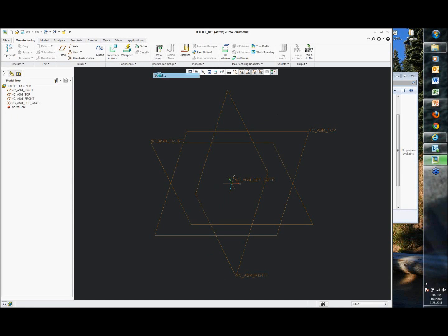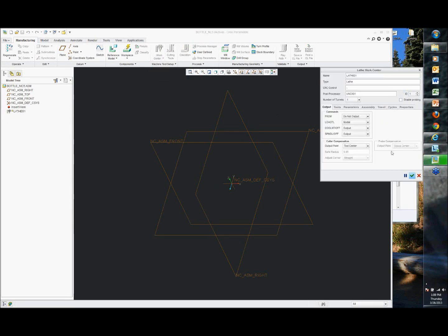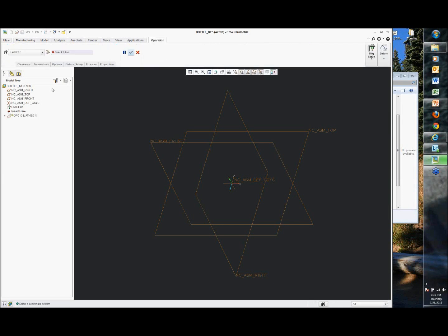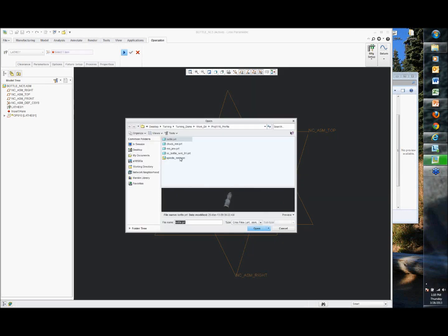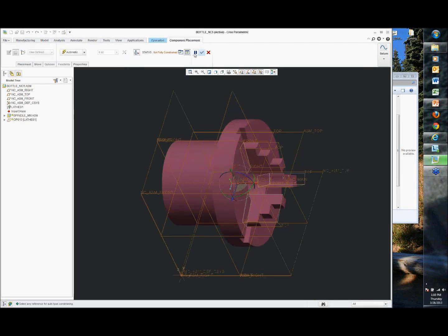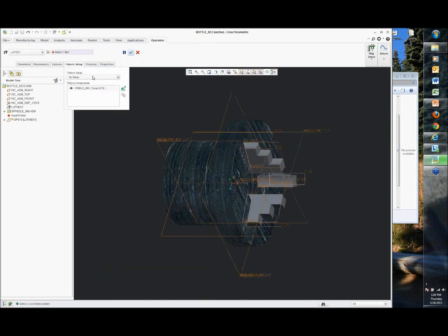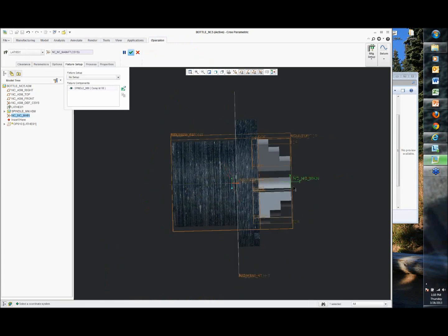So I'm going to go in here and just use a lathe tool. It's going to be a single turret, so I'm just going to leave this as a default. I'm then going to create an operation based on a lathe tool. Right, so it knows it's lathe 1. I'm going to add my fixture. So this is, again, all dashboard oriented here, so fixture setup. Go find my spindle. Go to assemble it. I know that I've got it all assembled the way I want, so all I got to do is hit default. Done.